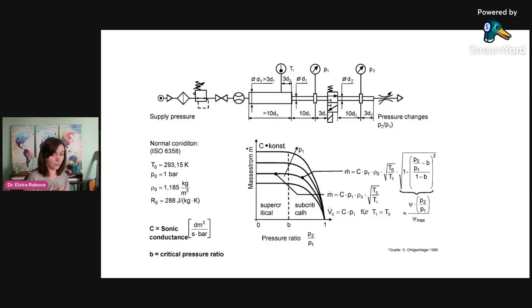So from the pure physics point of view, it doesn't make any difference if the pipe is too big or too small, only if you use it as the passage of the flow to some point of use until some pressure regulator. But of course, there is the cost thing. It's going to be more expensive, so you need to size it correctly.